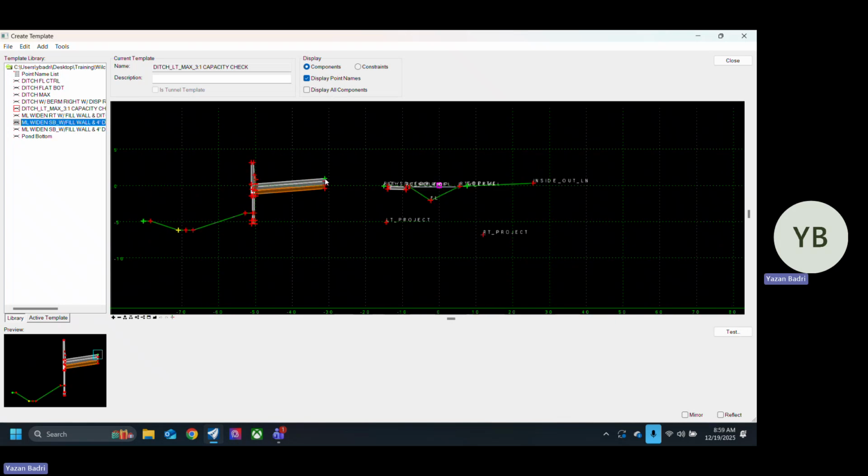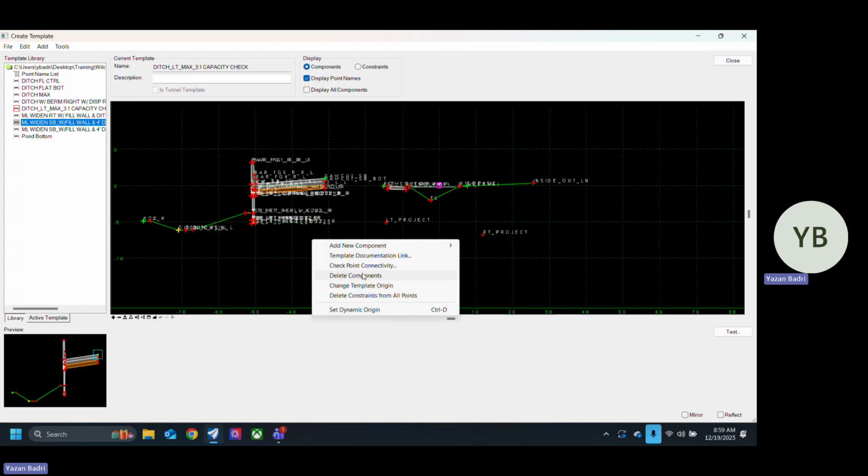I got you. So let's say you created your SSTR, right? You did it up to standard, you added all the curves and the details of a single slope concrete barrier. You don't want to do it again. So you can just create a component for that, like a template for that. And every time you want to use it, you just drag it and drop it and put it on top of your pavement.